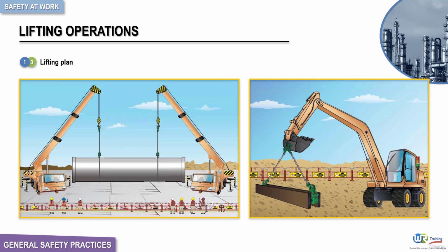However, if the lifting operation is unavoidable, a detailed plan should be made and approved by competent persons before the operation. In addition, for these special lifting operations, we strongly recommend the use of a walkie-talkie for communication instead of hand signals. The objective here is to avoid confusion or misinterpretation. In addition, only one signaler is allowed to give signals, and if the communication fails or the signal is unclear, the lifting operation must be stopped immediately.